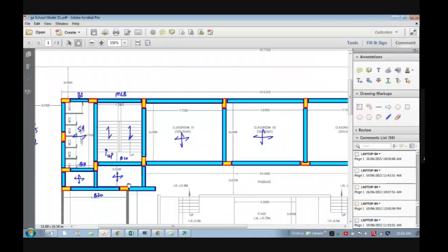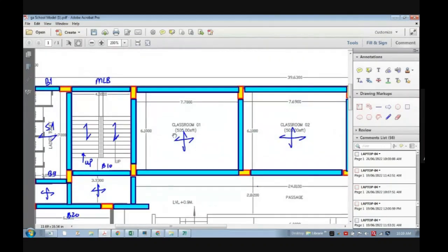See, generally we can design any kind of slab. There is no problem actually. As a structural designer, we can design anything. But just because we can design anything doesn't mean that you should design as you think. So you should think about the other parameters also while designing. So generally what happens whenever there is a big span, either it is a big span of slab or a big span of beams, when span increases, the deflection also increases. And as the deflection increases, bending moment increases, you need more thickness of the slab, or you may require more depth of the beams if you are designing a beam.